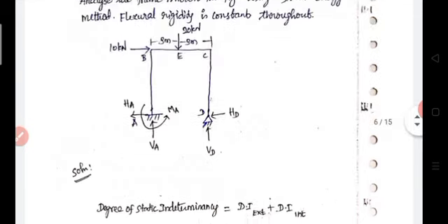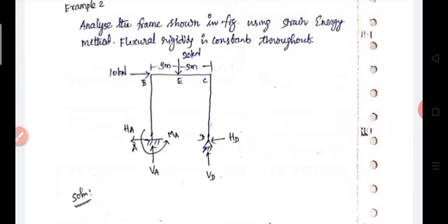In the portal frame, one end is fixed, another end is pinned, and it is subjected to a coplanar system. Coplanar is a two-dimensional, non-concurrent, non-parallel system of forces. Therefore the fixed support has three reactions: one vertical, then horizontal reaction, then moment. Then the pin support has two reactions: one vertical reaction, another one horizontal reaction.